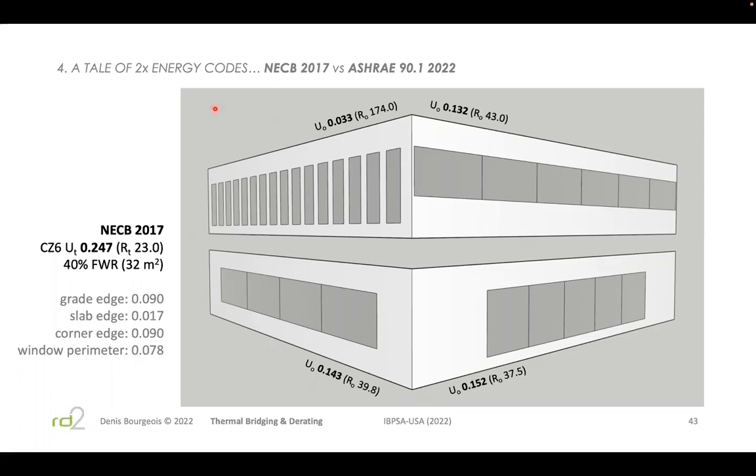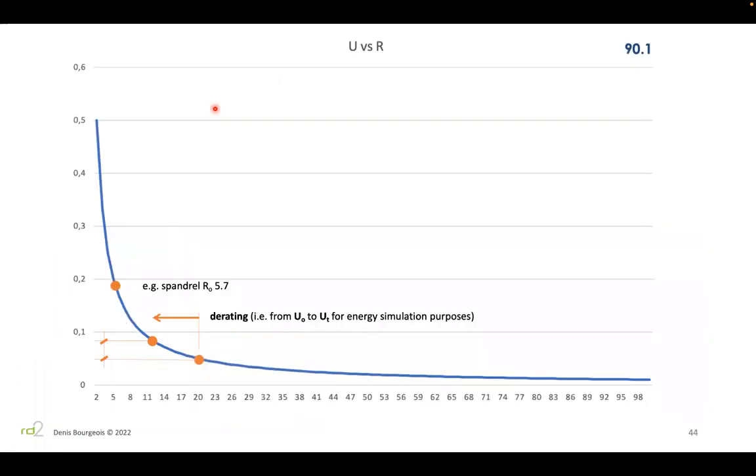Once you're moving in the opposite direction, those numbers are very low, the psi factors, but we have a lot of them and they add up. So once you start having significant weaknesses in your building envelope, any move towards higher performance is really a penalty. So I usually use these graphics to explain this to a client or an architect.